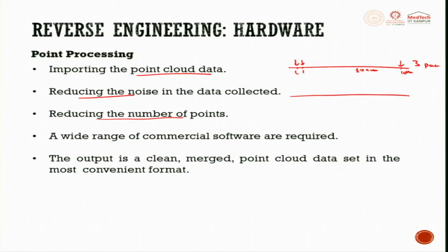In the analog system, if I have set the resolution or the point distance as 1 mm or maybe 2 mm, it will take a number of points here. So, this becomes a slower system at certain points if the dimensions are longer, but if the shape is complex, something like this, the analog system would move faster. It will take its points by itself, right?